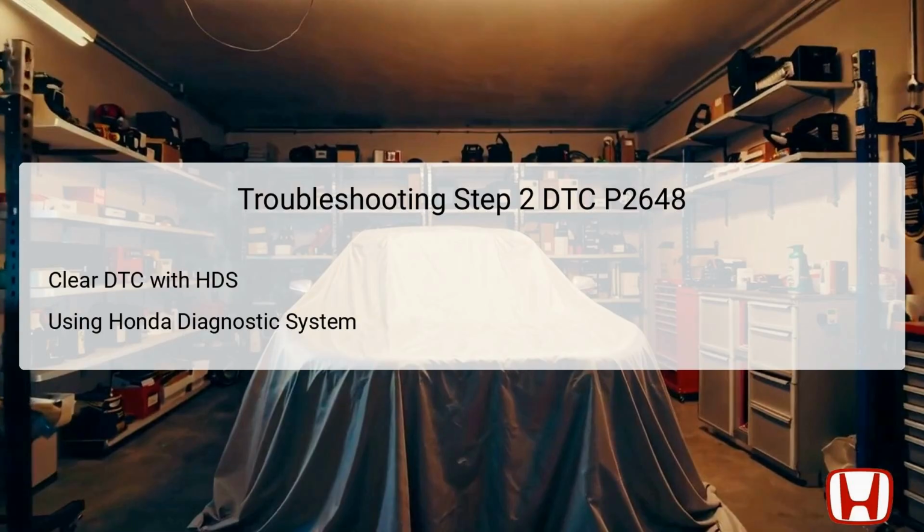Using HDS is crucial as it provides advanced diagnostic capabilities tailored specifically for Honda vehicles. Following this step ensures that any lingering faults stored in the system are cleared, setting the stage for more accurate testing and evaluations in subsequent steps. Properly using HDS guarantees that technicians can monitor the vehicle's responses effectively post-clearance.